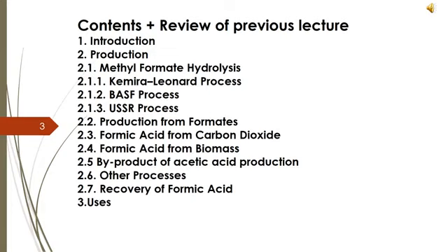When the reactor discharge is fed to E, the flash tank, some of the methyl formate, methanol or small quantities of formic acid evaporate, and they are then sent back into the main reactor. Now methyl formate and methanol are distilled in vacuum in the next column, whose name is the acid separator column.